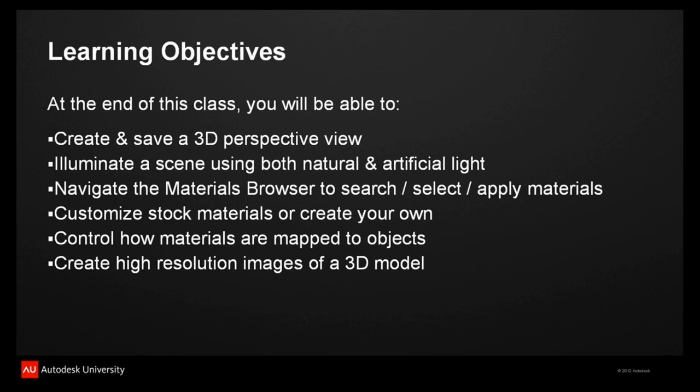We'll look at how we can search for items. I'll show you how we can apply those to our model. We will also look at how we can edit materials in the event shopping off the rack isn't exactly what we need for our project. We will also look at how we can manipulate the material once it's on the part itself. Take and shift it over, move it up, change the scale, things like that.